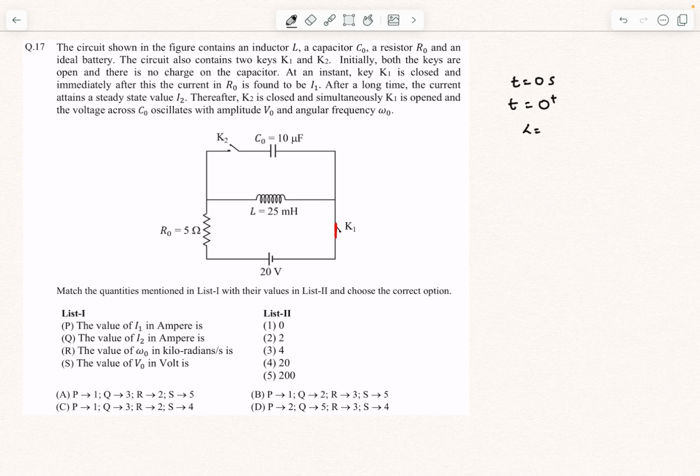One way is that the energy of the inductor is half Li squared, right? And in order to store the energy in the inductor, it does take some finite amount of time. By finite, I mean like 1 millisecond or something like that, right? So it cannot be instantaneously changed in a very short time frame.